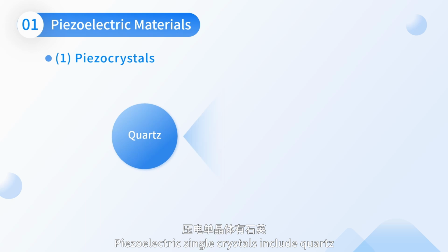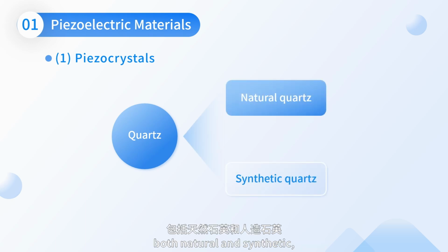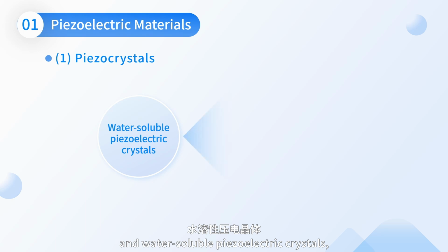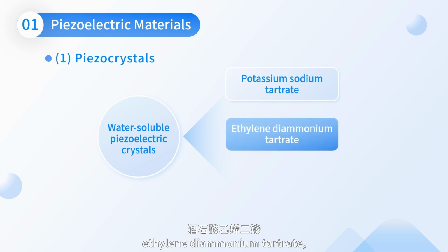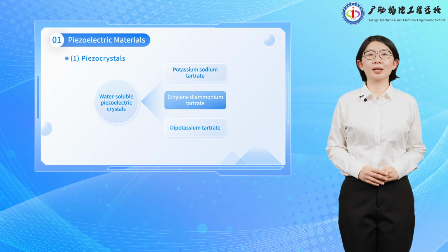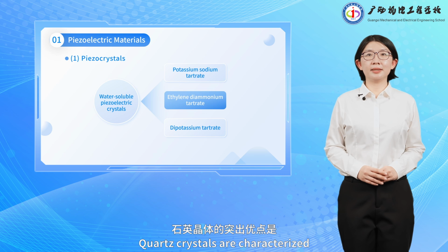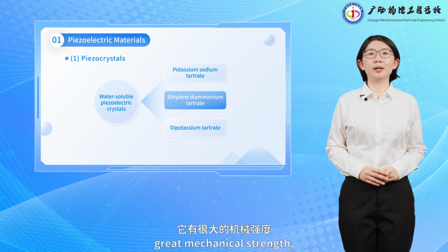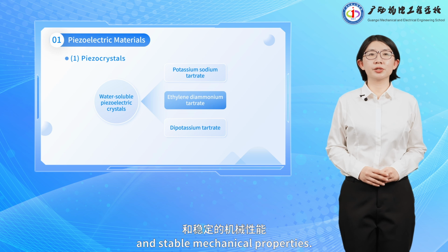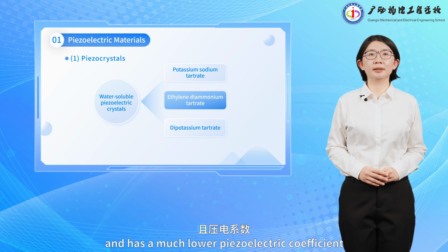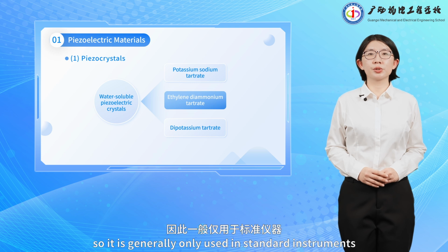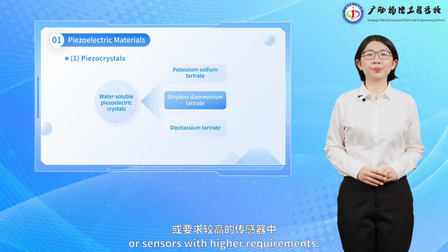Piezoelectric single crystals include quartz, both natural and synthetic, and water-soluble piezoelectric crystals, such as potassium sodium tartrate, ethylene diammonium tartrate, and dipotassium tartrate. Quartz crystals are characterized by their extremely stable performance, great mechanical strength, and stable mechanical properties. However, quartz is expensive and has a much lower piezoelectric coefficient compared to piezoceramics, so it is generally only used in standard instruments or sensors with higher requirements.